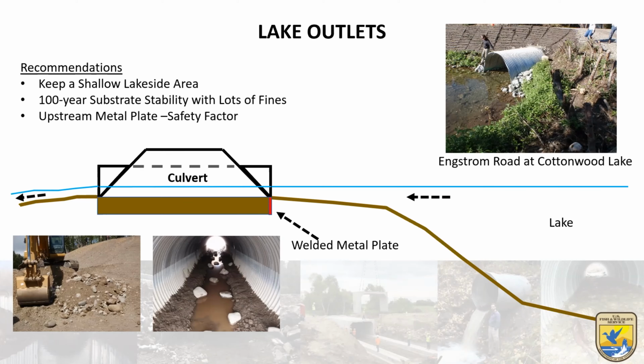We did put some habitat rocks in here because when you mixed all that up, it looked relatively uniform for some reason. And so we wanted to put some things in the low flow channel of this and provide a little bit of resting or break up the flow a little bit through that low flow. These things also help with predation. The theory being that if you're a small fish and you just have to be able to shoot through here, all the larger fish has to do is kind of wait at one end or the other or in the middle of the culvert. So you want a little bit of hiding areas for those fish.